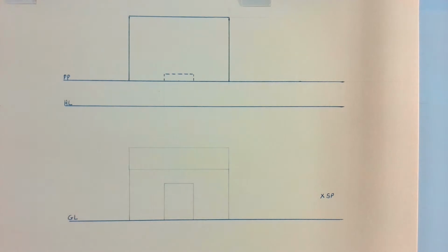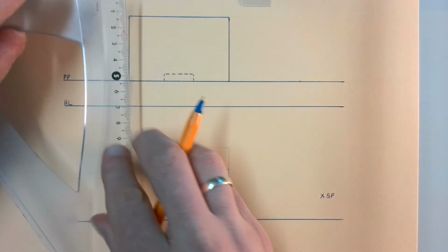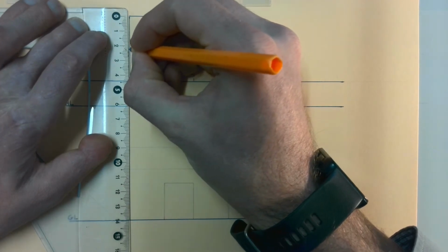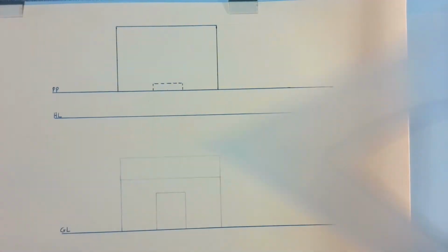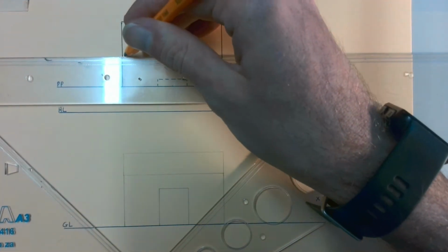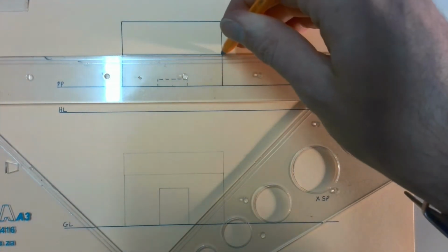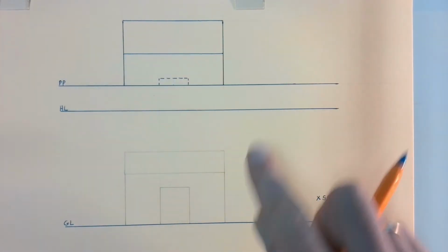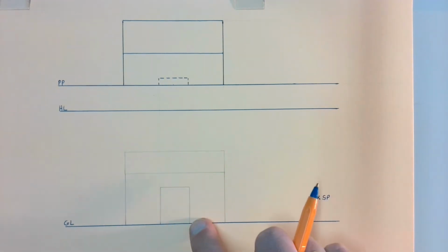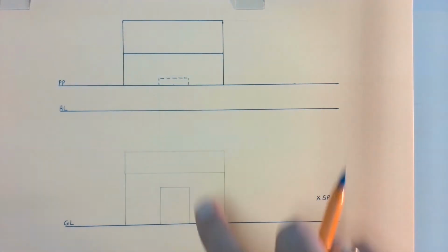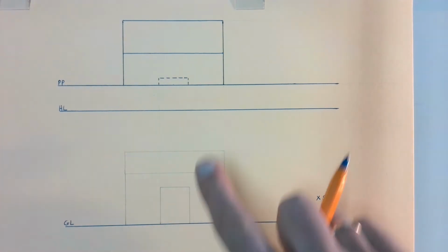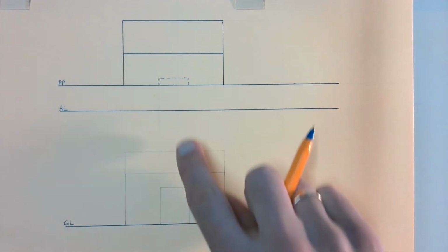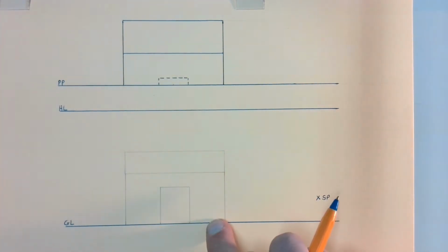This has got a roof which sits over here in the middle of this top view, and is a roof which is horizontal across like that. Okay, so we have a horizontal roof which has got a peak which we can see here in the front view. We have a doorway which you can see there's hidden detail, and the doorway here in the front view. And of course, if there's hidden detail shown in our top view, we know that this doorway is going to have to show some depth in our one-point perspective.